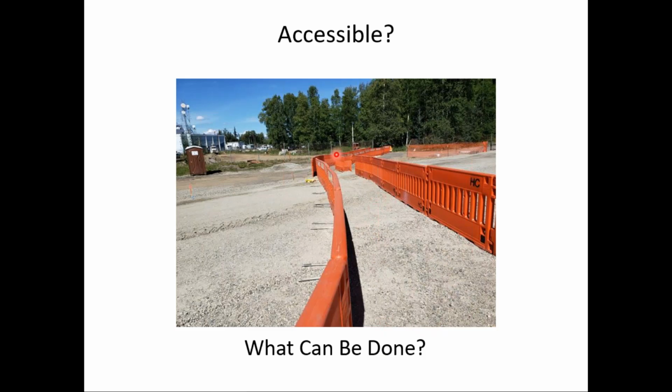There is a gap here, but otherwise it looks like they used the channelizers appropriately. They're interconnected. You can see they provide a detectable edge so that the pedestrian can follow the detour. They can do hand trailing. But the issue I have is, notice the surface is just stone surface. So stone by itself is not generally an accessible surface, or there may be similar issues.